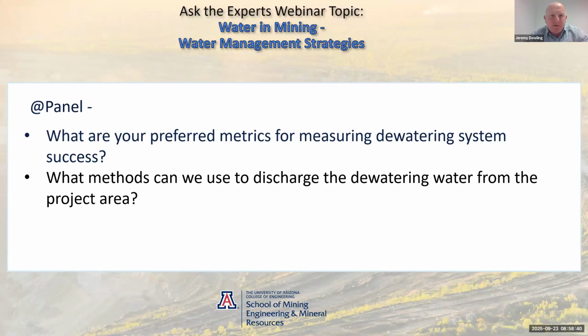No, I think just to add to what Jeff said, for any major pushback or pit design, there should be some assumed groundwater conditions in the geotechnical design analysis. At the most basic level, that will be a phreatic surface, or it could be a non-hydrostatic pore pressure profile.